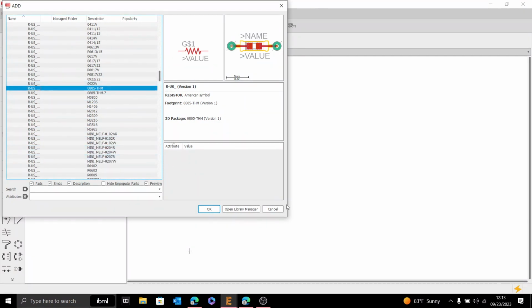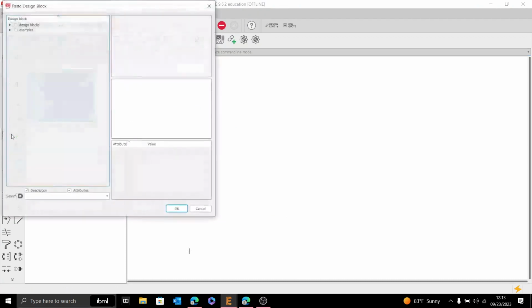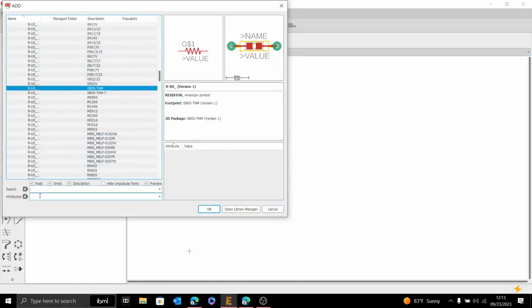Oh yes, so you got component sizes, all that good stuff. For a binary counter, we're going to choose, my trackpad is not very sensitive, unfortunately. So we are going to choose a CD4027.